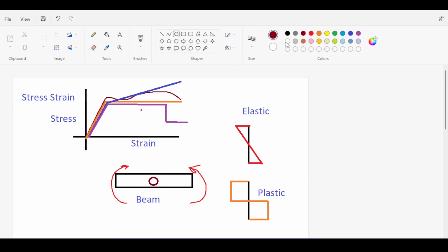Of course, you also have the option to cut off your stress strain diagram, which simulates the breaking, meaning that if you cut it off like this, then in that case the section will drop to zero because you assume that the section has been fully damaged. And this gets a little bit weird in terms of structural analysis.